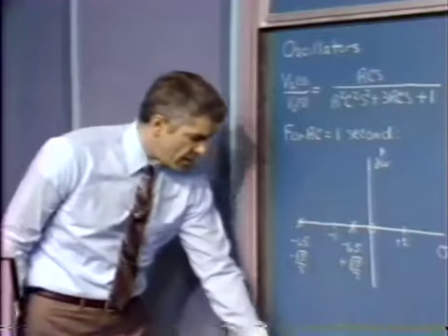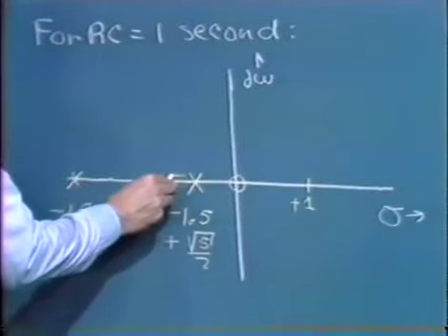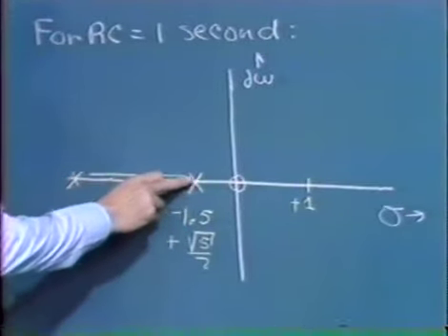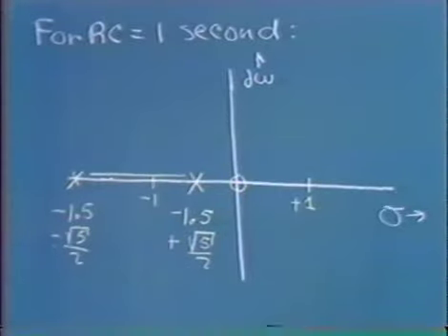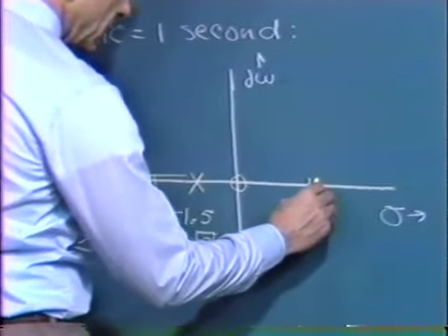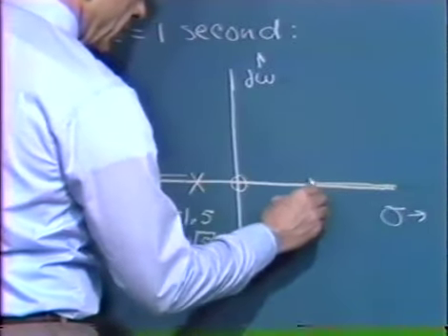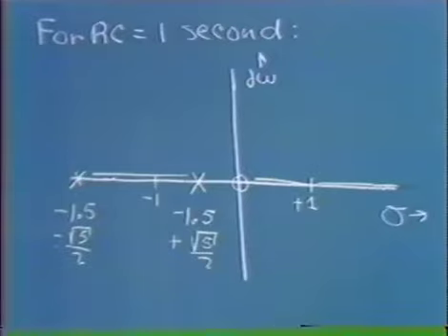So in this case, we have branches on the real axis here where we have two poles, one pole and one zero to the right. And they also exist on the entire positive real axis where we have no poles or zeros to the right, again, an even number.